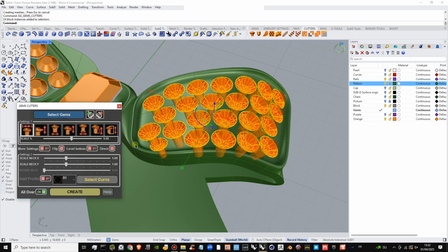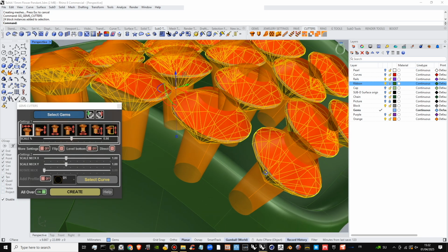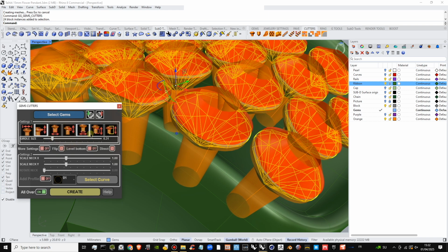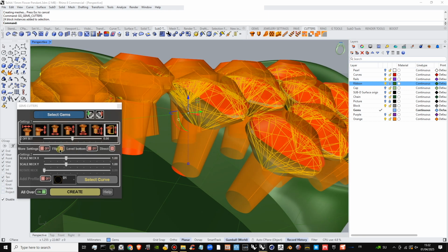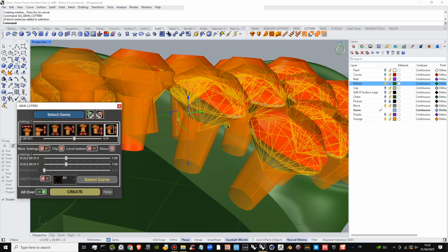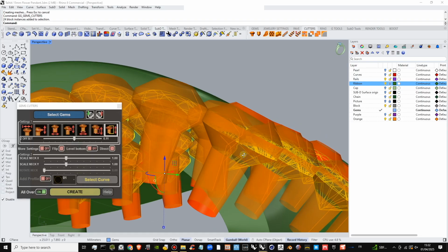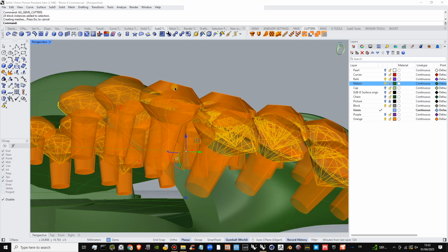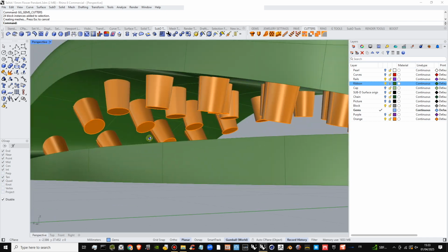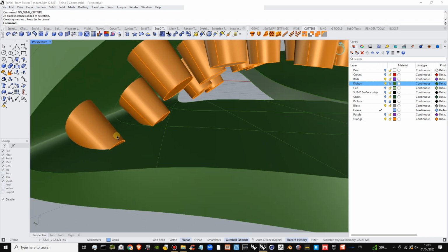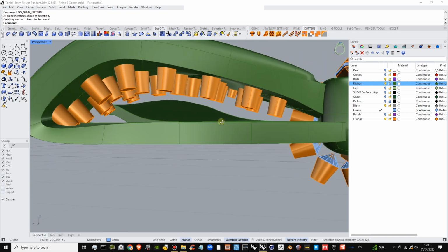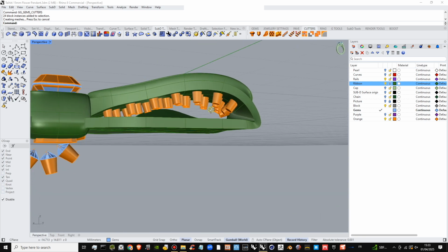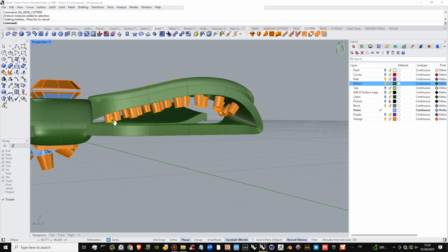Select the gems, and it does not remember that. So the girdle size, we have to bring that up, and then we have to move the height. So it's a matter of watching. Yeah, you will see if it's in line with the stone. So create, and we get. Now the next thing to check is that these holes don't, like here, cut into the other part of the surface, which you wouldn't want. There, everything's okay, nothing is cutting into anything.